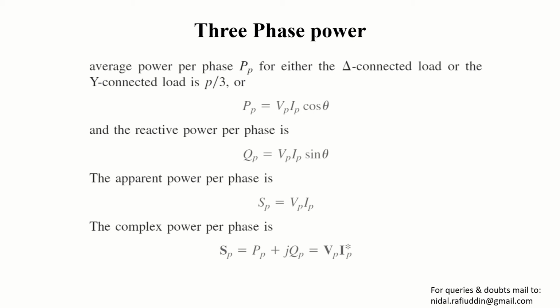If you remember, we talked about active, reactive, and apparent power in the one-phase system, and we saw that the apparent power was Vp Ip, simply the multiplication of voltage with current. If you multiplied this apparent power by cos theta, you obtained the average power, the real power, and for obtaining the reactive power you had to multiply Sp by sin theta.